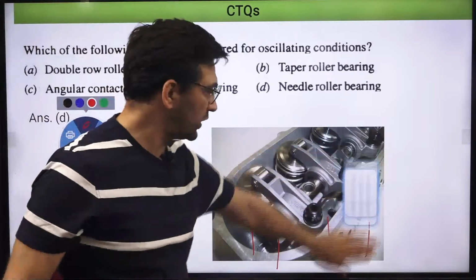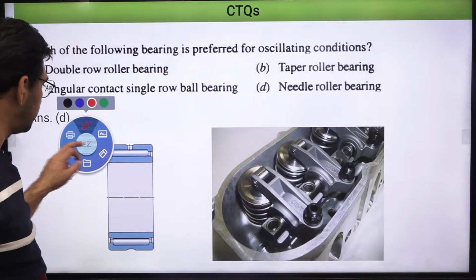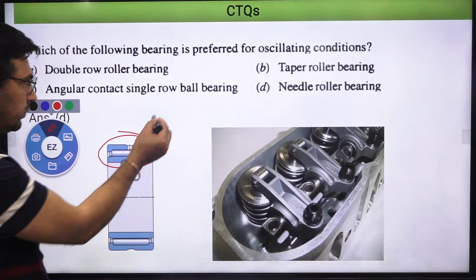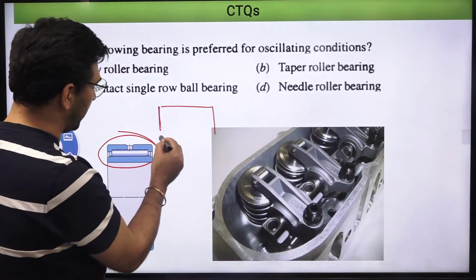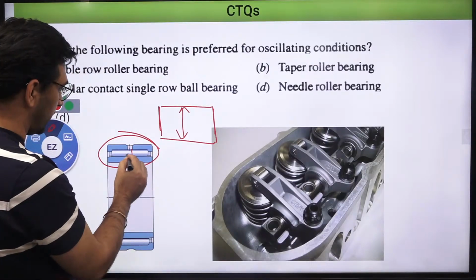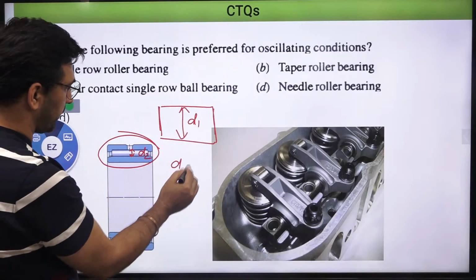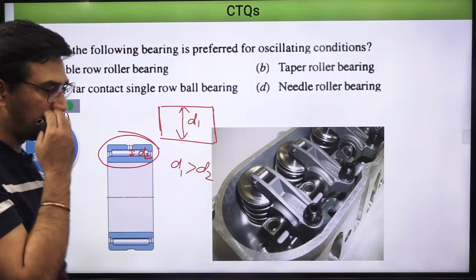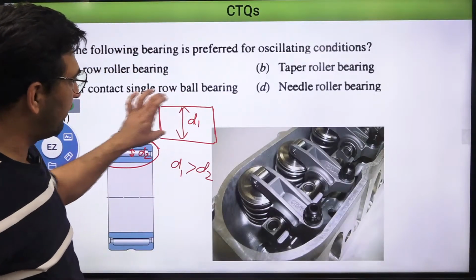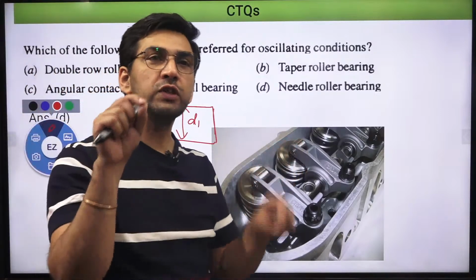For this kind of situation, specifically, this is one of the applications of needle roller bearings. These are roller bearings, like cylindrical roller bearings, but their diameter is relatively large compared to this one. Here the diameter is small, right? When the space is limited, we cannot have balls of a higher diameter. So normally what we do is employ rollers of smaller diameter.